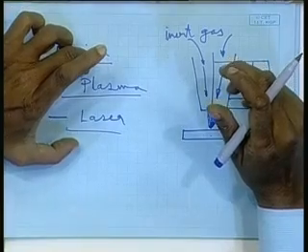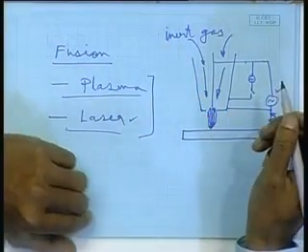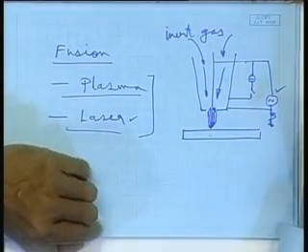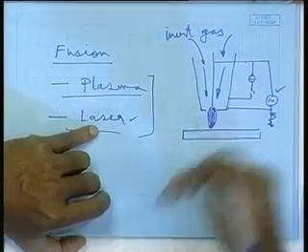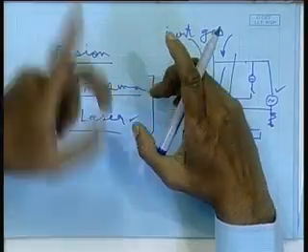In case of oxy you will have gas pipes coming in from the central supply. In case of plasma, you will have cables coming in. In case of laser, also some kind of cable will come in, right. That is the only difference. That means, in plasma or laser you have a high heat source. In some shipyards people have started using laser, but that is very limited, because with laser you can still have higher productivity, even higher thicknesses can be cut, but the cost increases exponentially, very high cost.